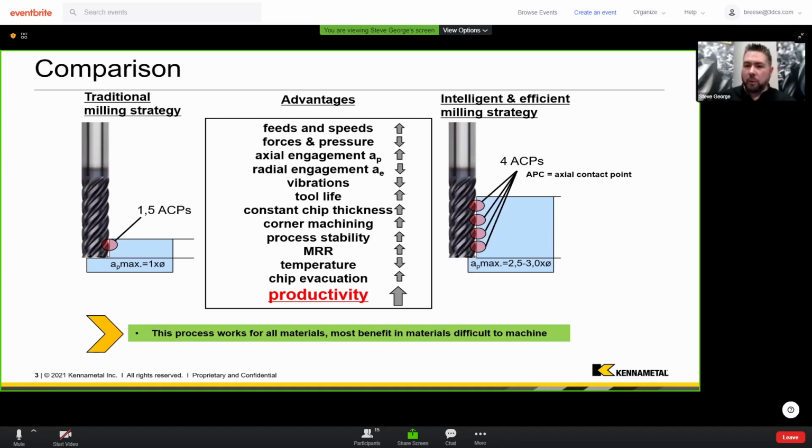That could be less if I want to be extremely conservative about tool life. That could be a little bit more depending on the material, if it's an aluminum, for instance, wrought aluminum, something like that. But as an average, I'm normally at 12, 13% as a general average, okay?